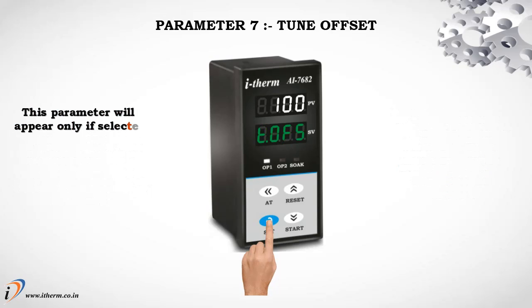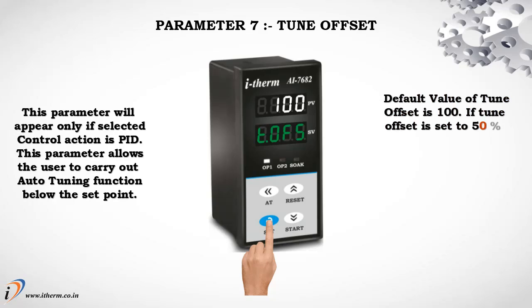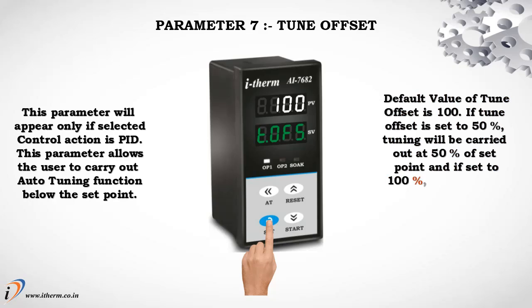Parameter 7, Tune Offset. This parameter will appear only if selected control action is PID. This parameter allows the user to carry out auto-tuning function below the set point. Default value of tune offset is 100. If tune offset is set to 50%, tuning will be carried out at 50% of set point, and if set to 100%, tuning will be carried out at 100% of the set point.